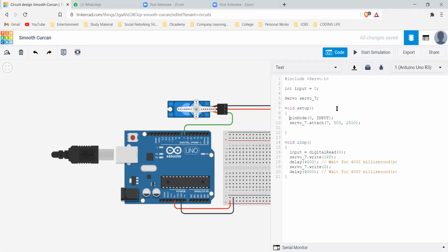Here we are setting pins. So what do you mean by setting pins? Okay, so as I said, there are digital pins and then there are analog pins. So how does the Arduino know that you have to read from it or give output to it? Okay, you do not know. The Arduino doesn't know. So you tell the Arduino that this pin is supposed to read input. This pin is not supposed to do anything else but just read input.